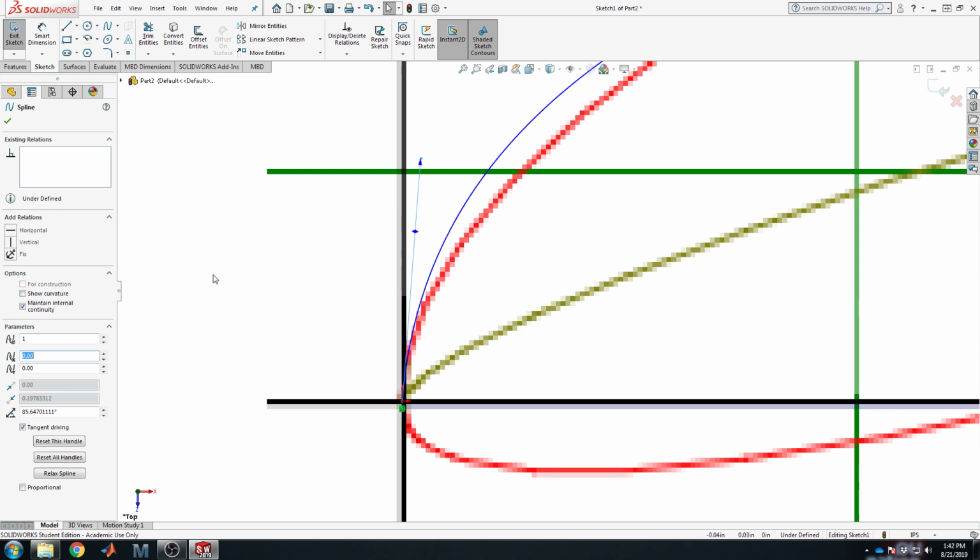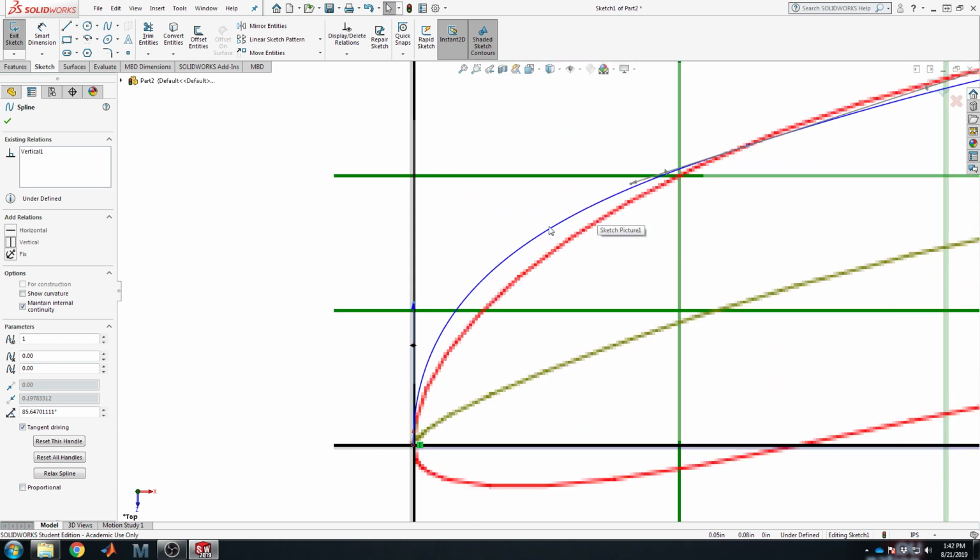But for the leading edge point in particular, I usually try to make it vertical. You want both the top and the bottom lines to depart from the stagnation point, that 0, 0 coordinate point, in a roughly vertical orientation. And now I just adjust the length till it more or less matches, biasing my adherence here to the front portion, more or less matches the airfoil shape.